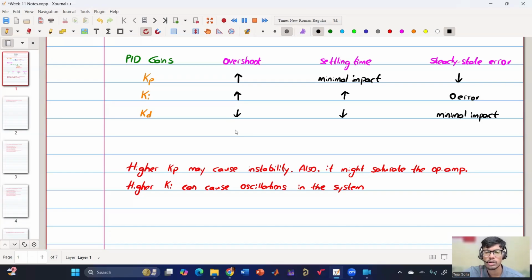So now the control voltage will change and then some duty ratio will change and then the system will respond to the dynamics. Say if my KD is 100, then it will become 100 millivolt. 1 millivolt noise can become 100 millivolt and then now the system will respond to that new control voltage. So KD can amplify the noise, which is also not good. So high KD is not at all good, even though it will reduce the settling time.